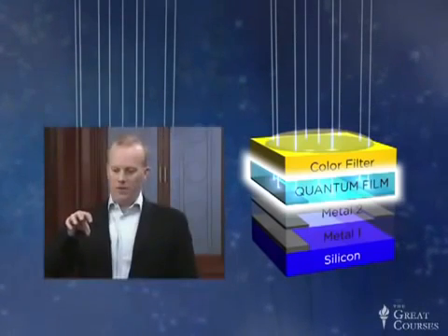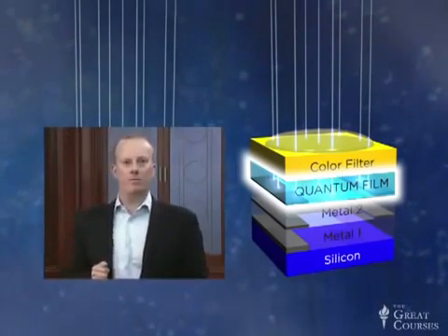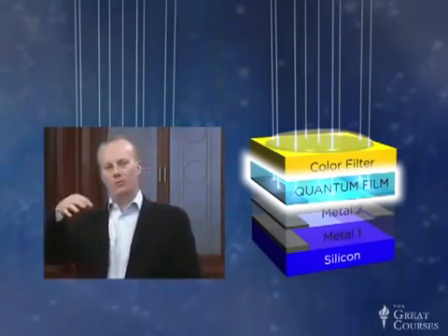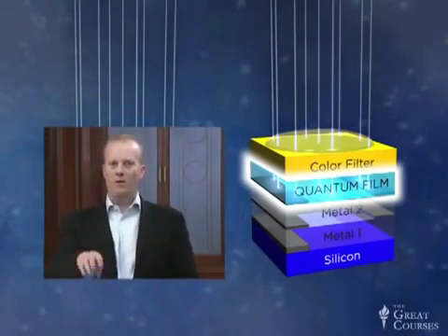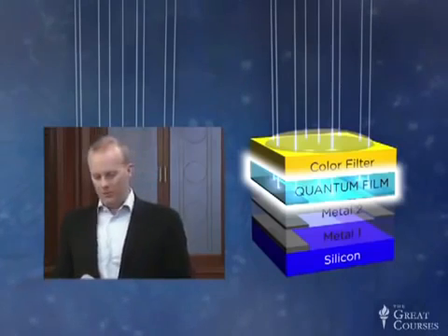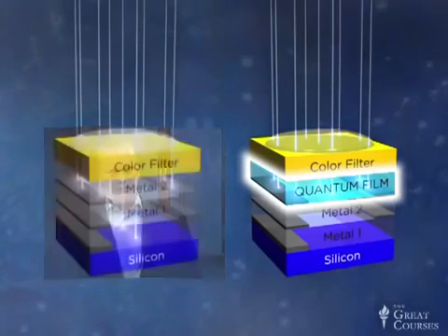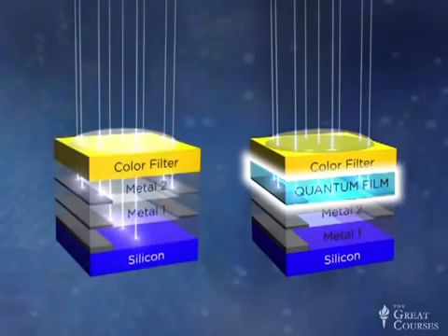And so now, as shown with this film at the top level of this nano-enabled integrated circuit, we're able to absorb the light closer to where the light is coming from. The light's no longer responsible for passing through these layers of wire, for passing through an optical aperture, and then being absorbed in the silicon beneath. Instead, we bring our sensor closer to where the light impinges from. So this is a first advantage. This use of nanomaterials overcomes the fill factor problem.